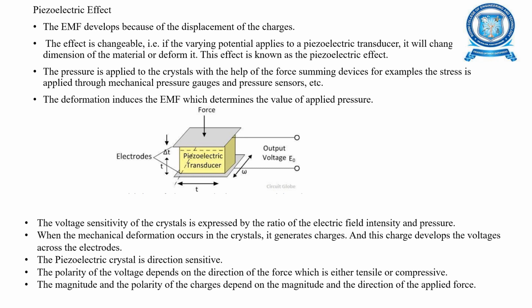In the diagram you can see the force is given and the changes in the size, that is deformation, and the output voltage gives the piezoelectric effect, that is EMF is developed. The voltage sensitivity of the crystal is expressed by the ratio of electric field intensity and pressure. The piezoelectric crystal is direction sensitive. The polarity of the voltage depends on the direction of force, which is either tensile or compressive.